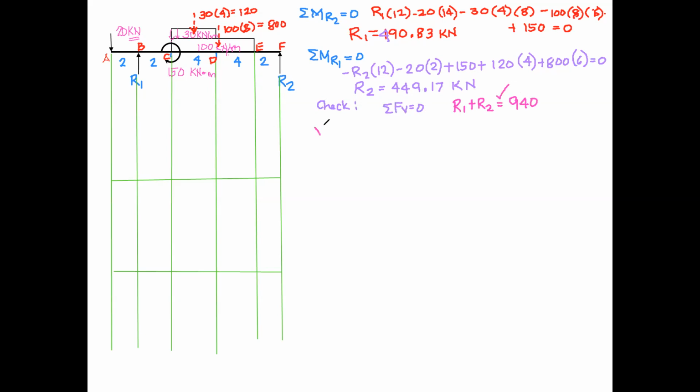So shear. Okay, so we need to determine where do we get the left and the right? Saan ba tayo mag-analyze ng left and right? Dapat naintindihan din yun. Shear ordinate. Anybody? Okay, so meron lang analysis ng left and right sa mga points na meron tayong concentrated load or reaction. So dito, it's only at A, B, and F. Tama.